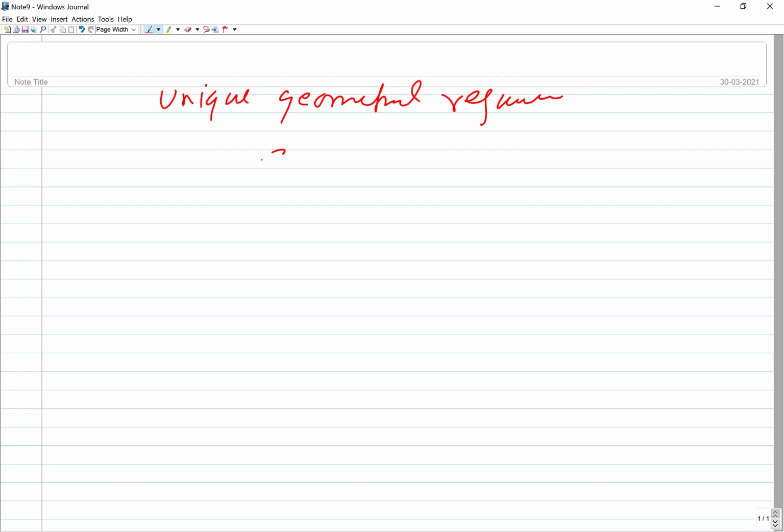Normally we make a hole of 1 mm, 1.5 mm, but if you want to make a hole of 10 micrometer, and that too with say 10 mm depth, how will you do it? You cannot do this easily. Maybe a 1 mm hole of say 2 mm depth is workable using drilling processes, but a very fine hole size with very large depth, very high aspect ratio, is certainly not doable.